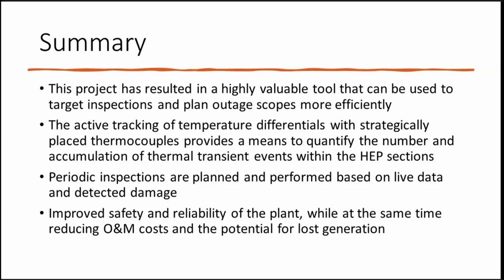So it's a very low energy, and as Eugene said, there's not enough energy to require post-weld heat treat, even on P91 materials. It's basically the same technique you see the post-weld heat treat contractors use when they spot weld thermocouples onto the part that they are heat treating. We just make it a little more robust by the way we tie down, insulate, and put an expansion loop in the wire.